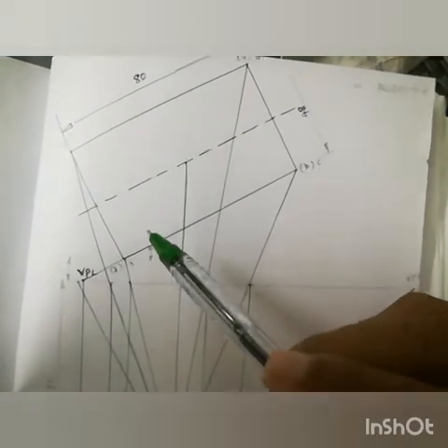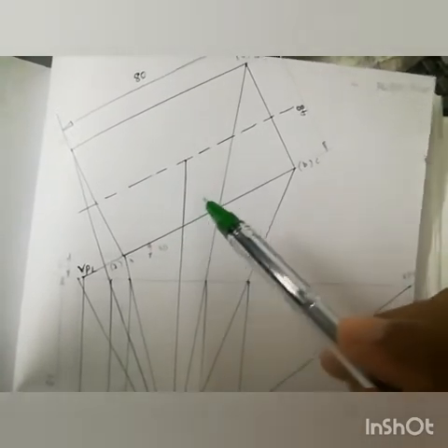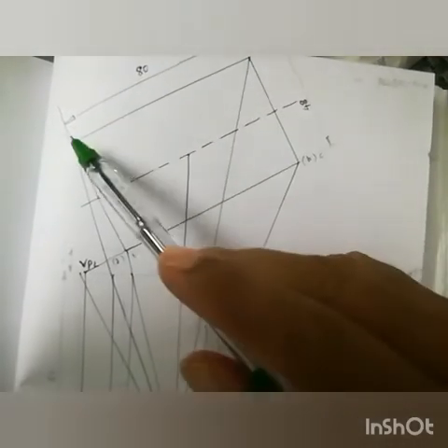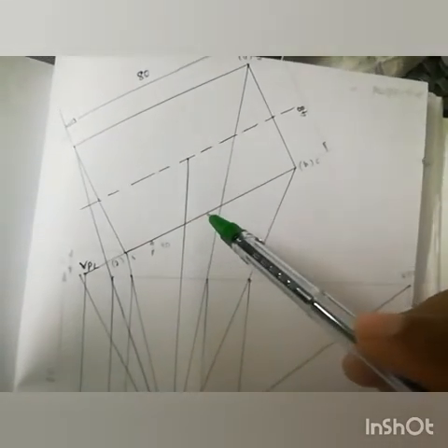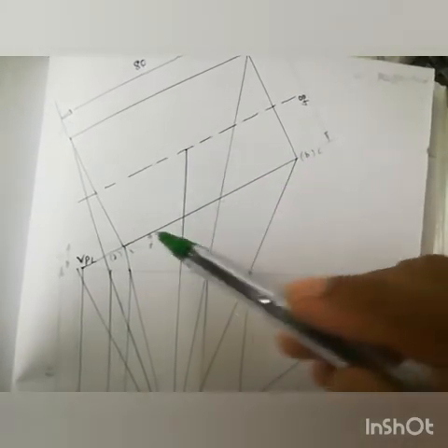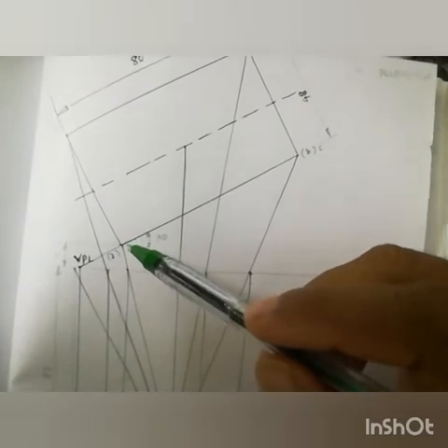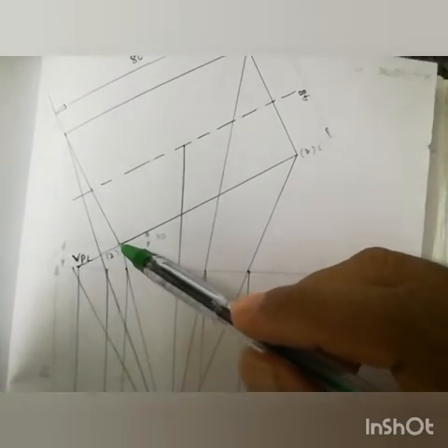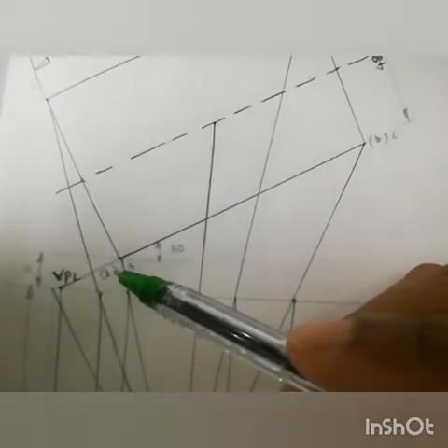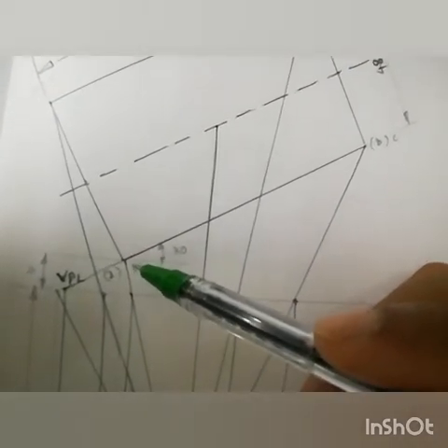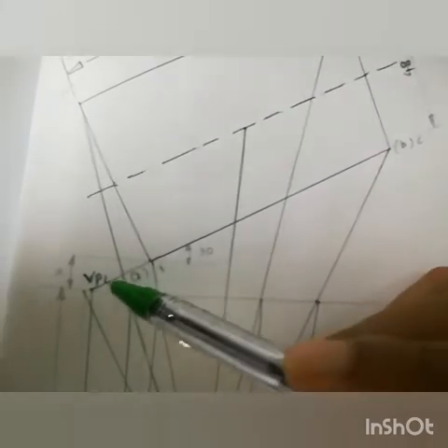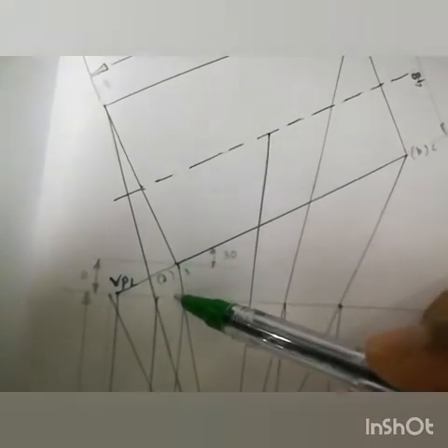The larger face is on the ground, means its dimension is 48 by 80. So this is 80, this is 48. That's the larger face. That is, it is lying on that larger face with the longest edge, with a vertical edge 10 mm behind picture plane. So this is 3 edges. This is bottom 2, 3, top 3. This edge is vertical and it's 10 mm behind. This distance is 10 mm behind picture plane.